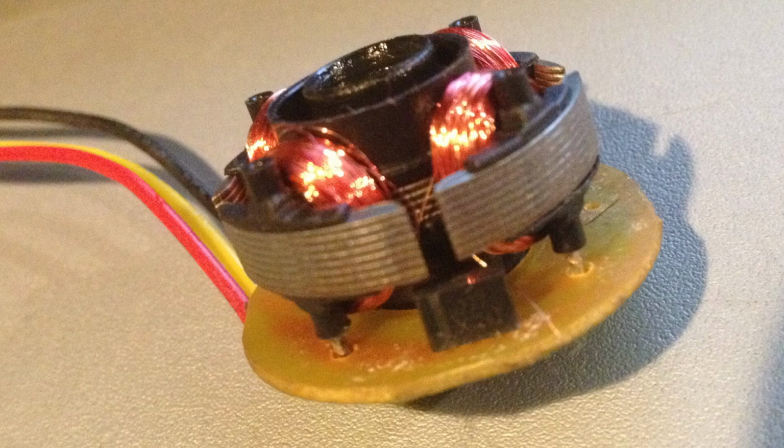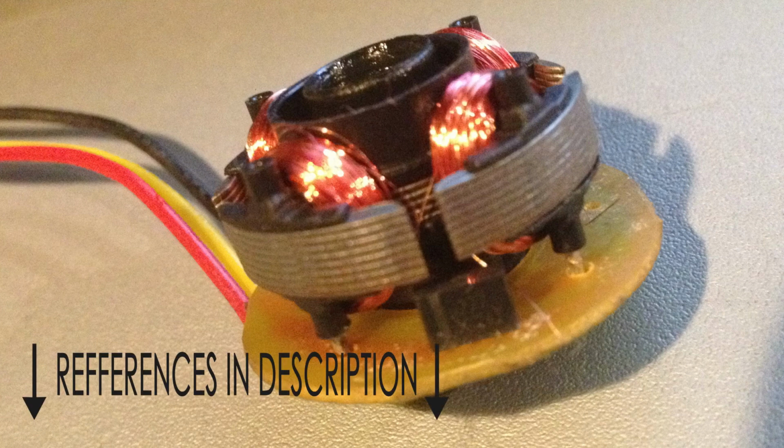It is slightly different from what I just explained, as the outer magnets rotate around the electromagnets, rather than the electromagnets being part of the rotor. This negates the need for brushes, however this means that the electromagnets need to switch their polarity in time with the rotation of the fan. The computer can also control the speed of this fan by changing the rate that the electromagnets switch polarity.